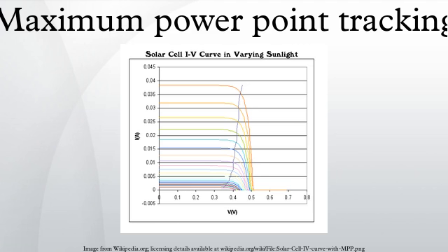The latter technique is referred to in contrast as the open voltage method by some authors. If the output voltage is held constant, there is no attempt to track the maximum power point, so it is not a maximum power point tracking technique in a strict sense, though it does have some advantages in cases when the MPP tracking tends to fail, and thus it is sometimes used to supplement an MPPT method in those cases.